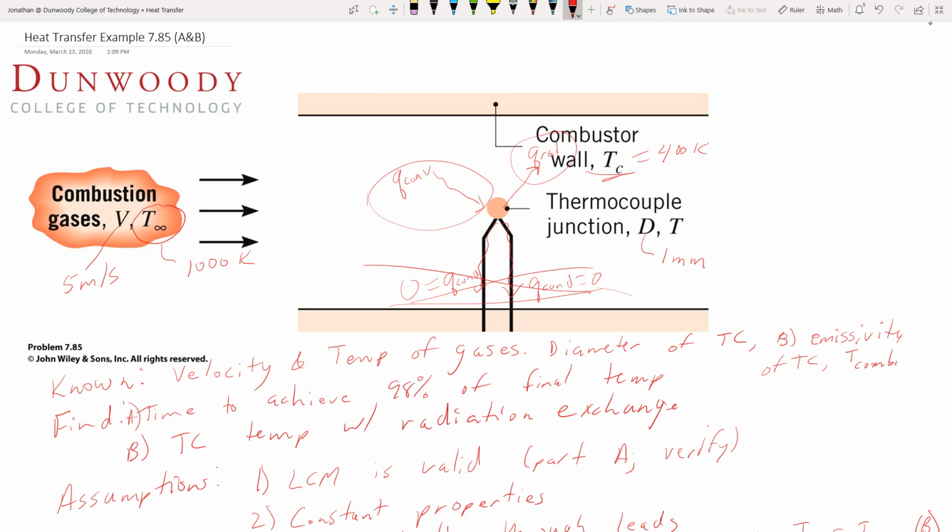Nothing surprising there. If our emissivity was bigger, what would you see? Well, we'd see that temperature difference go even lower, right? That would pull this down. If our emissivity was lower, it would be closer to our actual measured temperature.